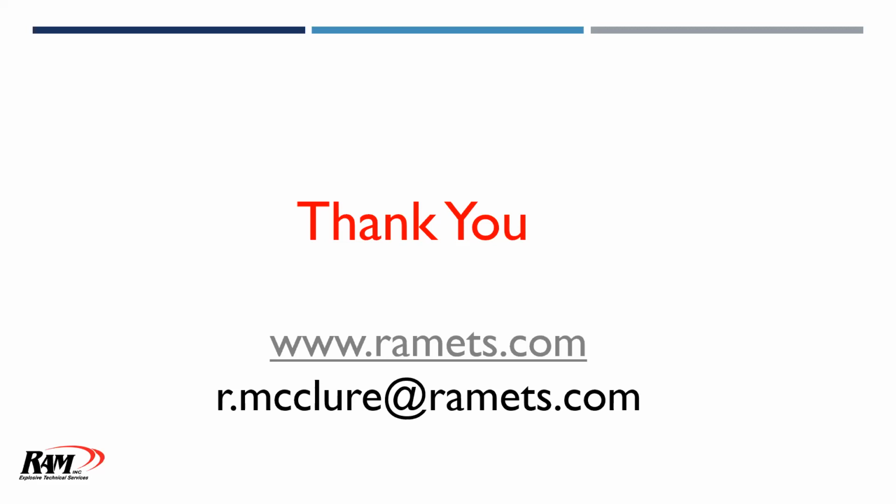But the other way you can do it is if you're in a situation like I mentioned early on, where you have no survey capability at all, we can set targets up with a set scale on them and fly it and capture those targets. And you can get a very accurate survey, but it will not be georeferenced. It's going to create its own local coordinates. And so it's possible to do that and do a good job with it.